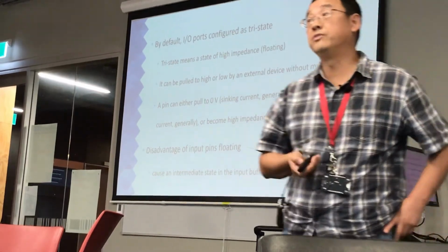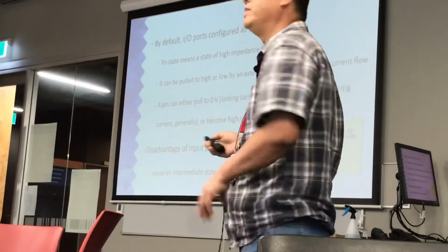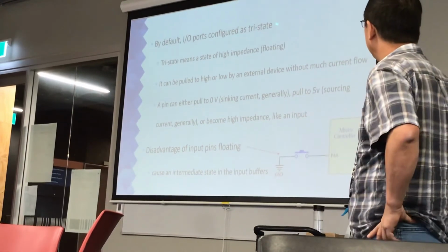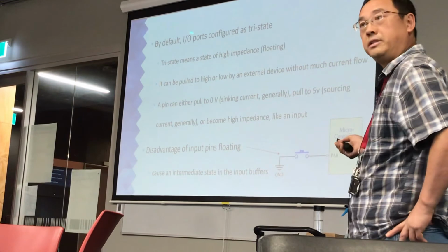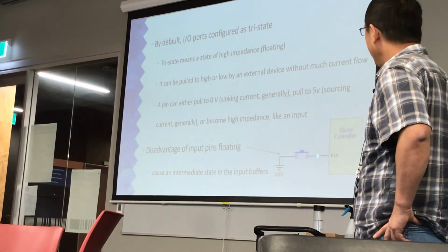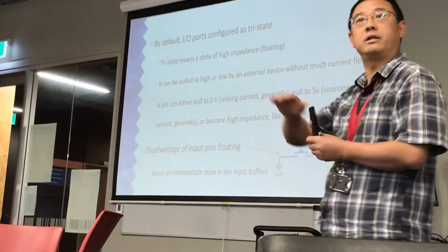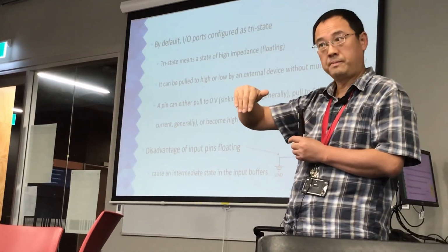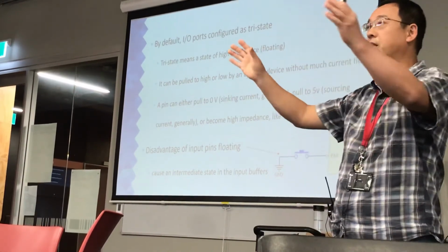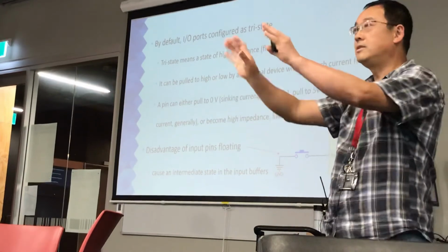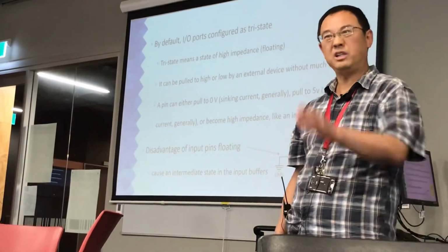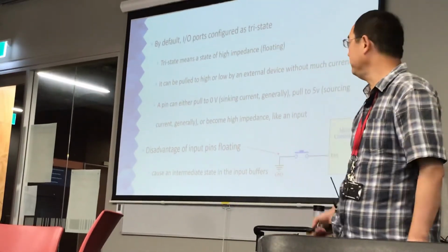There is a disadvantage to that. Because the pin is tri-state and high impedance, a little bit of noise can change PA0, making it go either high or low. If the input pin is floating, you can have a problem.